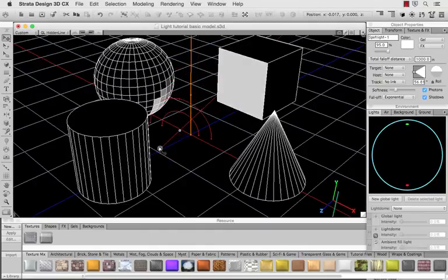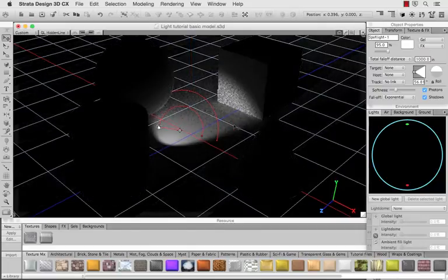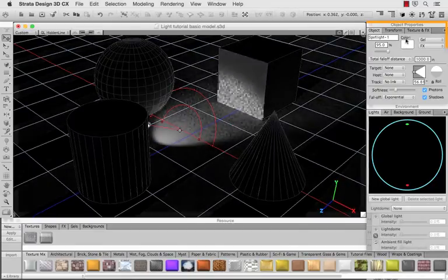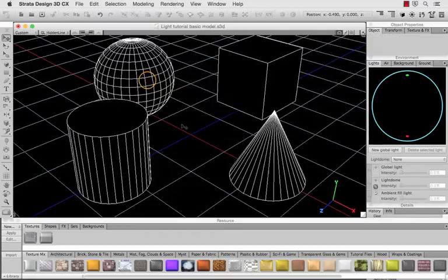One quick way to raise an object off the active grid is to hold down the Command and Shift keys while you drag the object. This enables a temporary guide that's perpendicular to the active grid. Like the point light, there are many options available in the Object panel of the Object Properties palette. You'll want to review the user guide for more info on those.